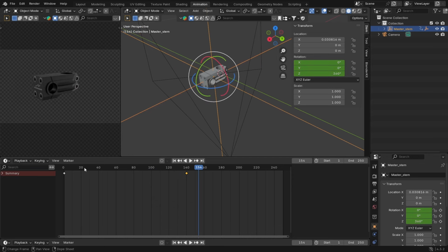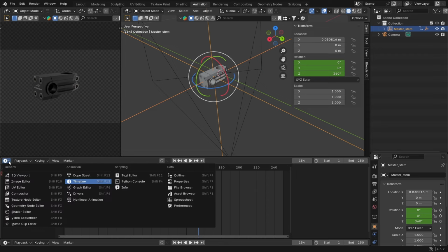Did you notice the animation speed isn't consistent? It starts slow, speeds up, and then slows down again. This isn't a problem for translating objects, but it is for rotation for me. This is a default Blender setting. To fix it, you need to go to the Graph Editor.